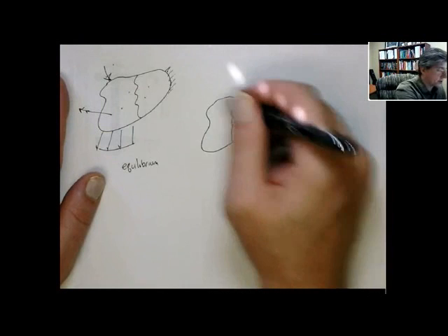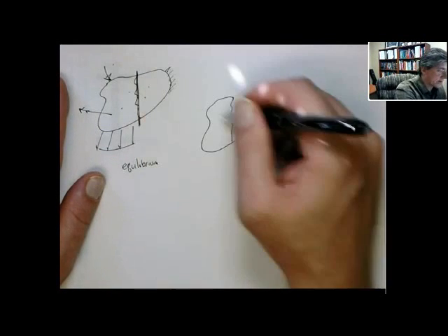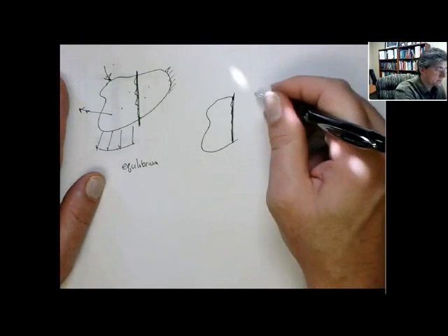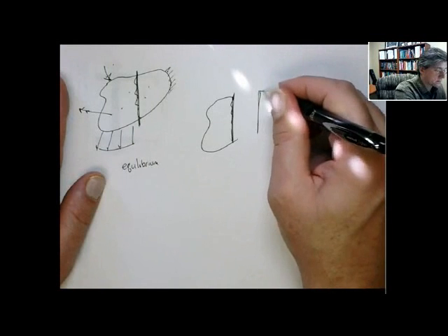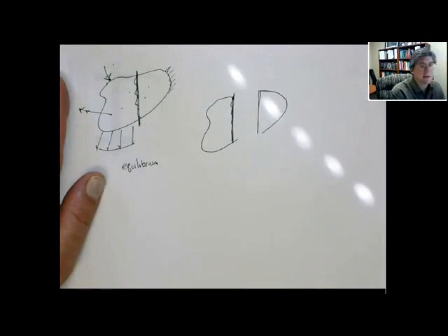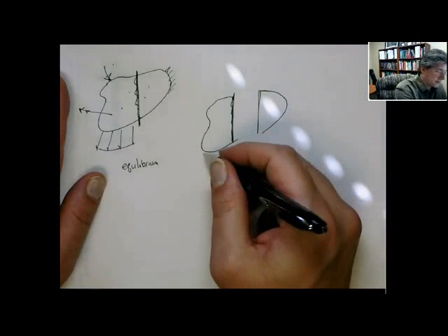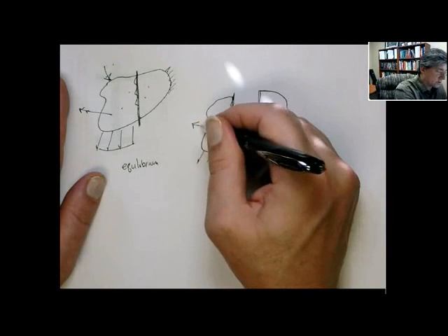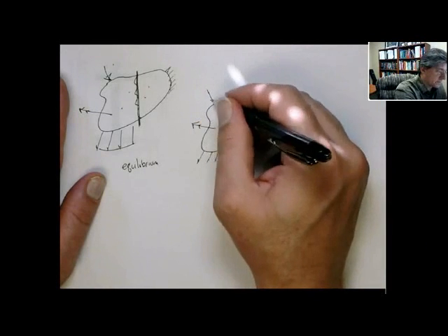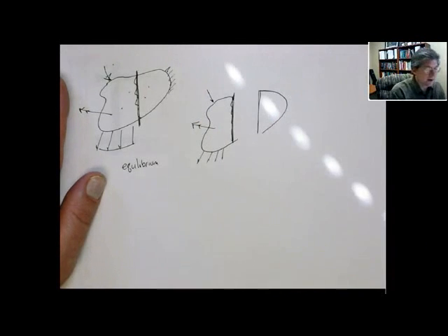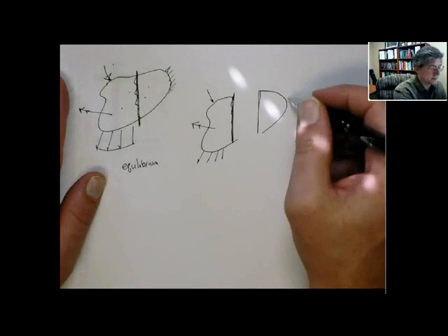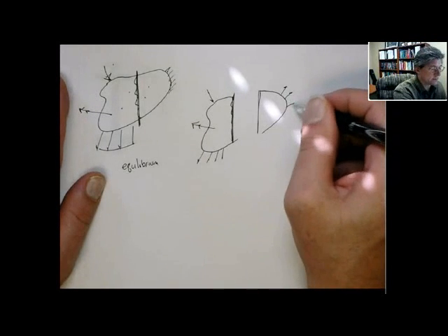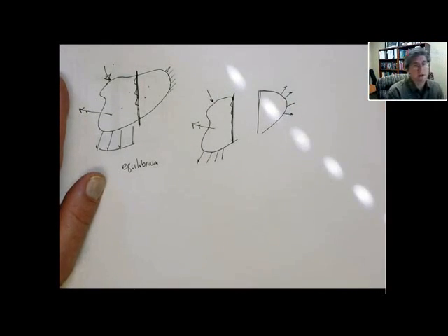Usually I draw this flat. Let's imagine it's a flat cut, makes a lot more sense. It's supposed to be the same picture, but split. And here are those external forces. And now to make it a proper free body diagram, let's not put the constraints, but let's put some reaction forces that correspond to that fixed condition.